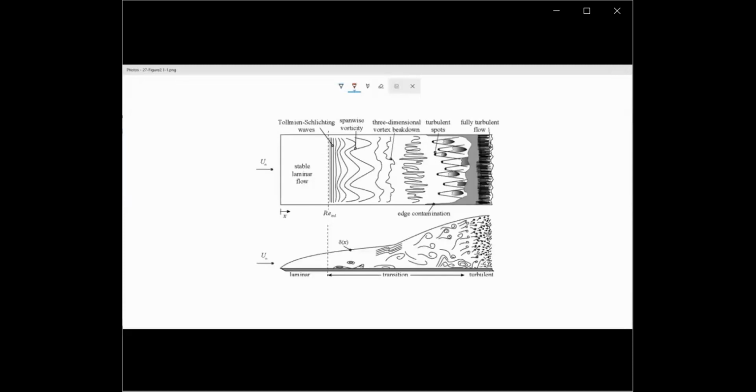Now, the last topic is, of course, that we know boundary layers come in different shapes and sizes, meaning that over a flat plate or over any solid body in general, the viscous effects happen inside the boundary layers, but the boundary layer characteristics could be quite different. The velocity profile, the approach of Blasius and all that, assumes that we have what we call a laminar boundary layer. The flow is laminar.